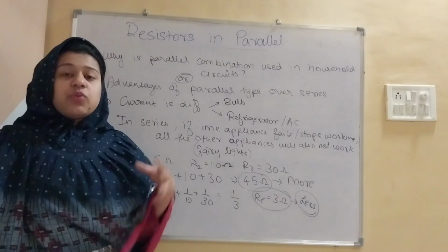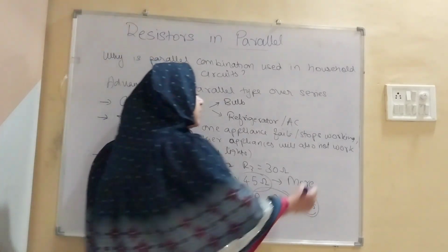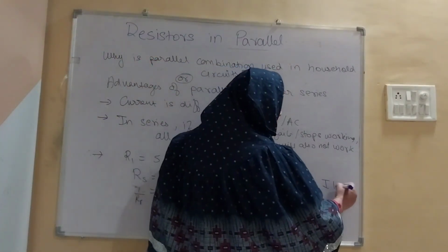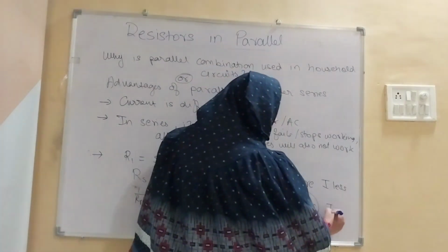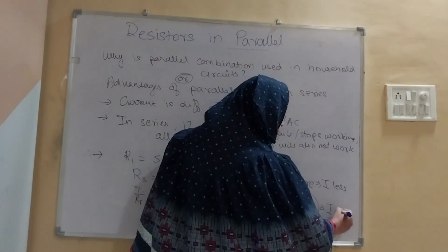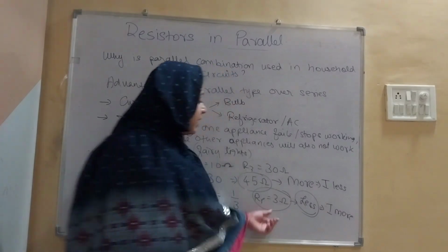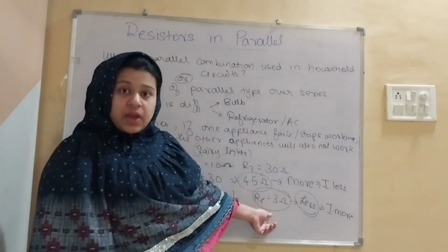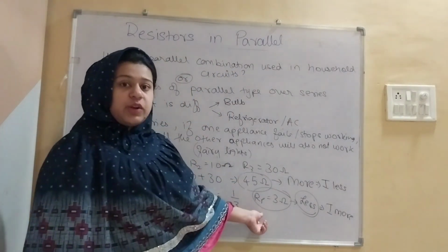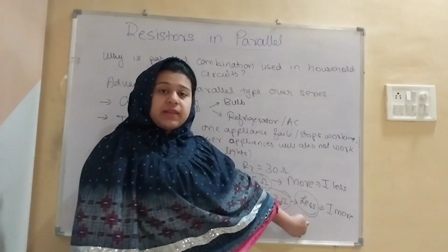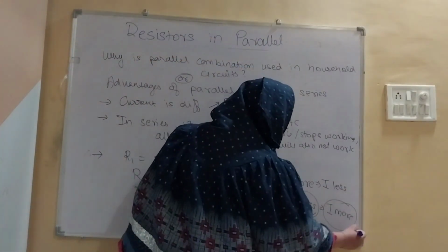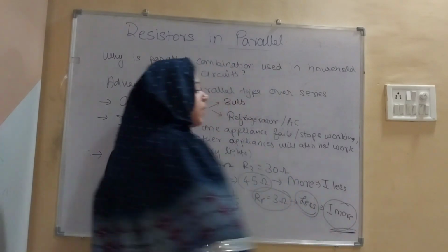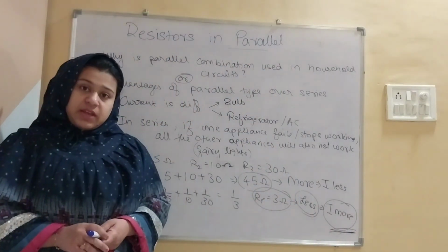अगर रेजिस्टेंस ज्यादा होगा, ऑब्स्ट्रक्शन इन फ्लो ऑफ करंट ज्यादा होगा, ठीक है, रुकावट ज्यादा रहेगी तो करंट कम फ्लो होगा, सो करंट विल बी लेस, और अगर रेजिस्टेंस कम रहेगा सो द करंट विल बी मोर। तो अगर हम पैरेलल टाइप ऑफ कॉम्बिनेशन यूज करते हैं तो उसमें जो इक्विवेलेंट रेजिस्टेंस होता है, टोटल रेजिस्टेंस, वो बहुत कम रहता है, इट इज वेरी लेस, एंड सो द करंट फ्लोइंग इज मोर, तो हमें बहुत ज्यादा करंट मिलता है। ठीक है,